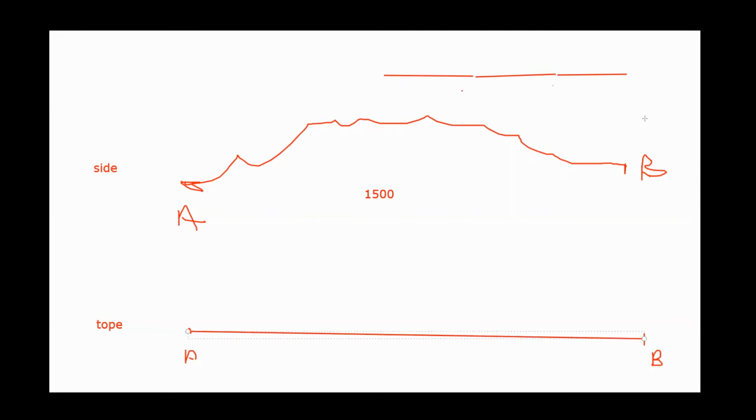Now let's put our tape. The first segment starts from here to here, and then the second segment goes from here maybe to here. You can't really align your tape exactly on the line because the line is not marked on the ground. If the line is marked on the ground, that's great, but that's very rare. So these 2 points, you can't see them from each other. If you stand at B, you can't really see A.